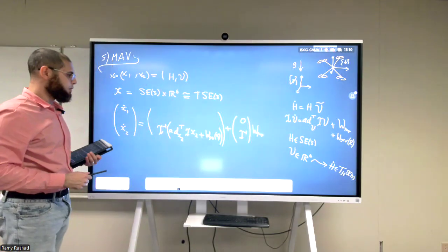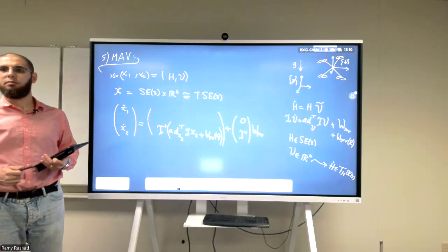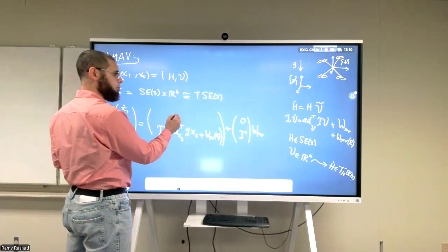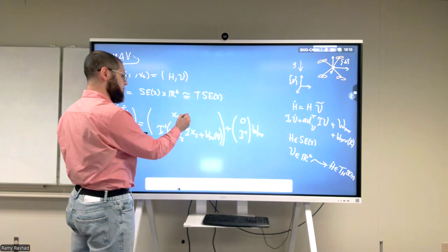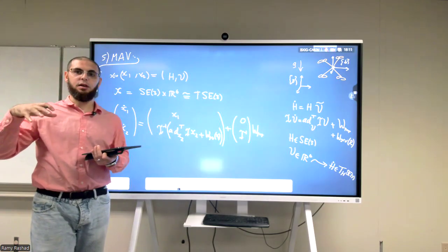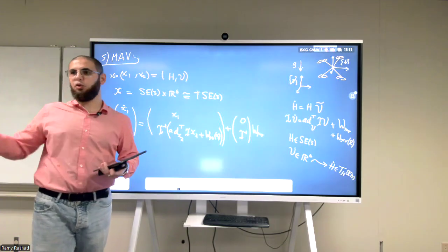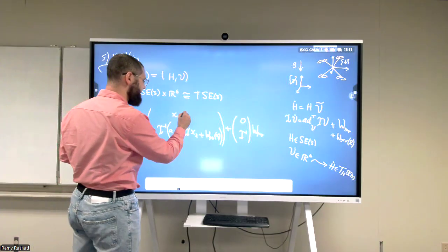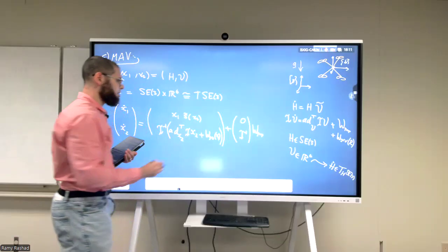Okay. What about the first equation? What is actually the first equation? It should be x1 multiplied by, it's not the skew symmetric form. It was the tilde form of the twist, which was a 4x4 matrix that had the skew symmetric omega next to it, the V, and then the zeros on the bottom. So multiplied by, we called it the S tilde of x2, you remember? Something like this, right?